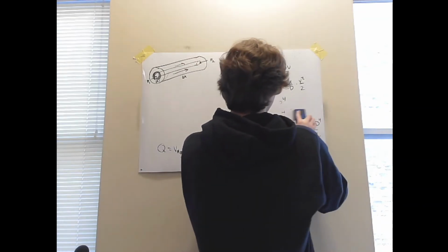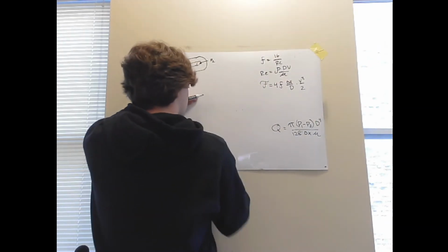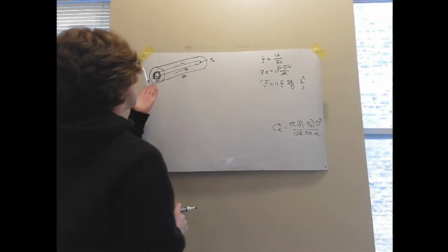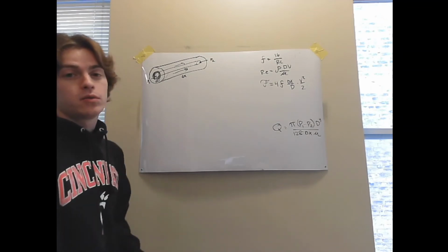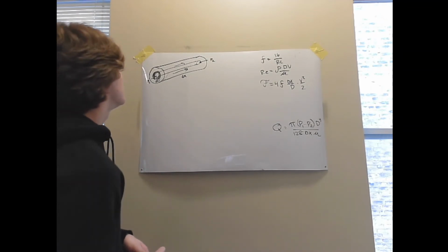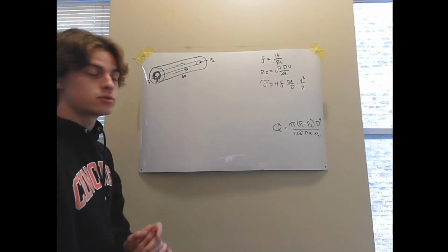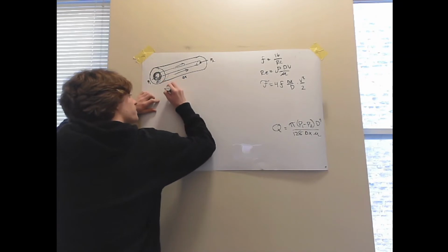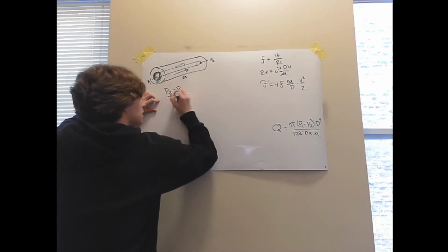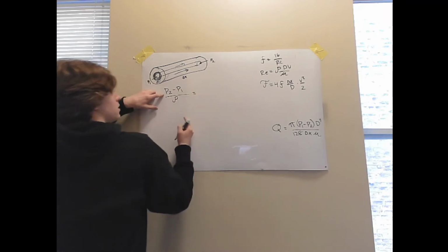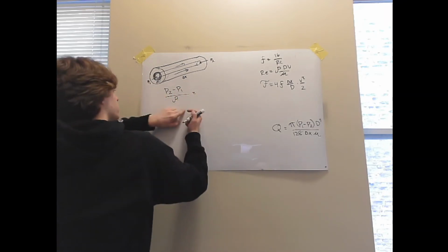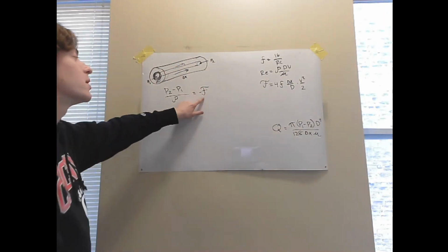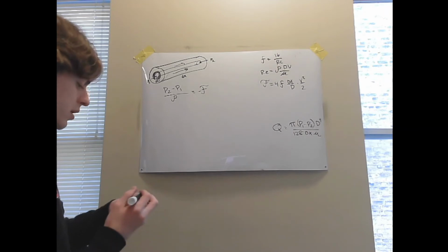So now, like I said, from here, we can go ahead and apply Bernoulli's equation to this problem. And since the diameter is not changing, we don't have to worry about change in velocity. And since our pipe is flat on the ground, we have no change due to potential energy. So for this problem, Bernoulli's equation is just going to be the pressure at location 2 minus the pressure at location 1 over the density, equals the negative friction factor, frictional heating coefficient.